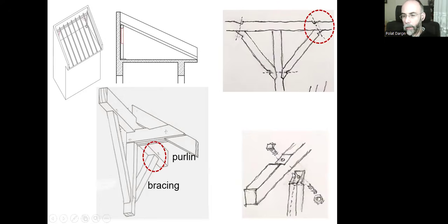And in its opposite direction, we can create the mirrored version of this groove on the bracing here. This way, we will have a straight line in which we can drill a hole so that we can place this long bolt and secure this nut tightly, like that.